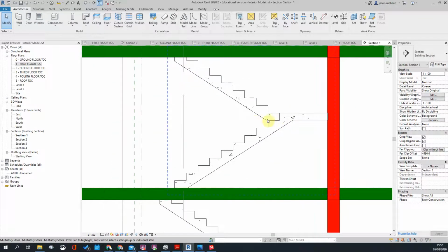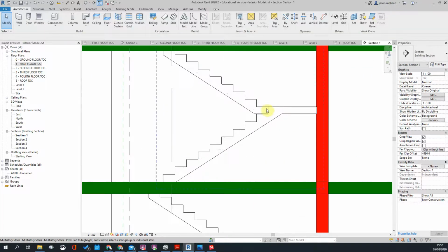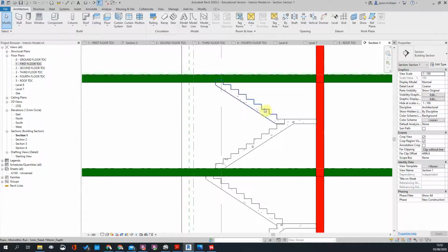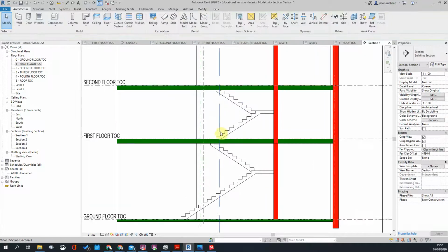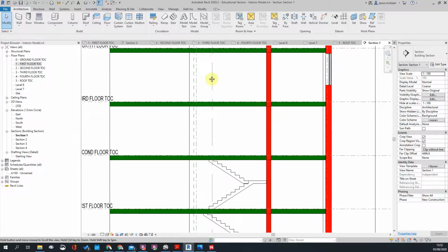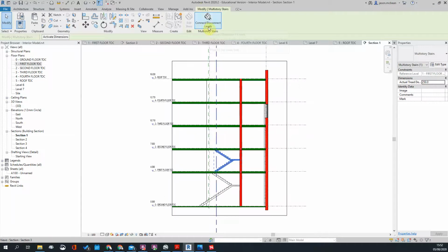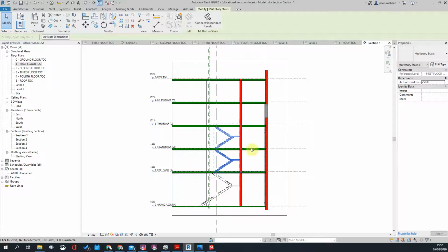You can either make it on the landing this side or on that side. I'll make a call, but I'm wondering if maybe I make a longer landing on the one side. So that's how you get these to end, especially if you've got a staircase where you've got a shaft. You want your slabs to stop in the same line, and that this stair will then be duplicated. And because there's a function that you make it a connected stair, it means you can connect the different floors. So it will keep replicating.